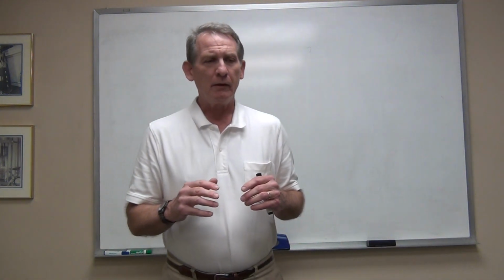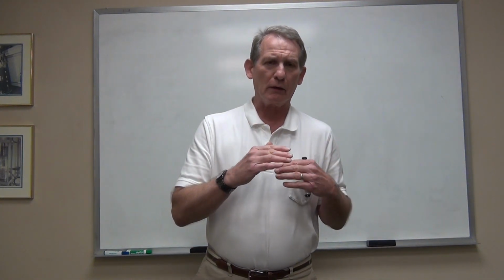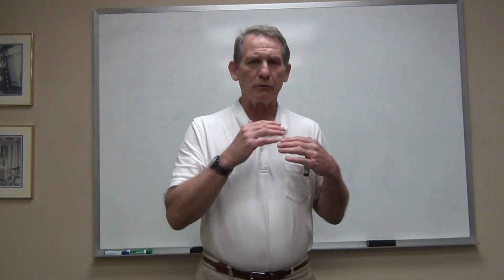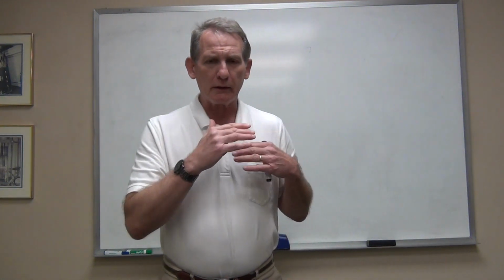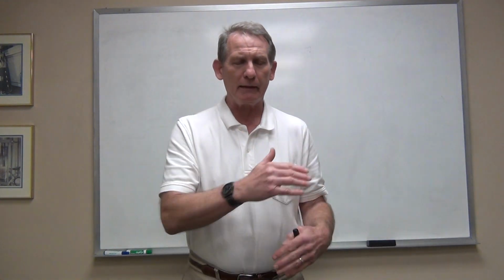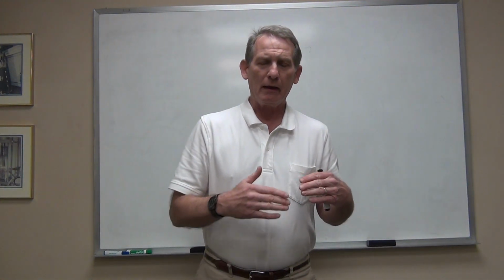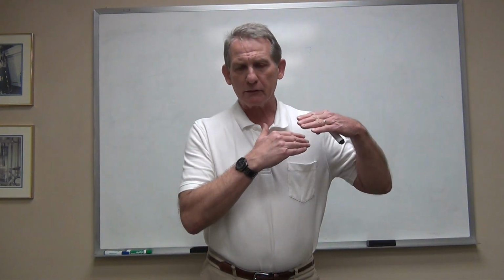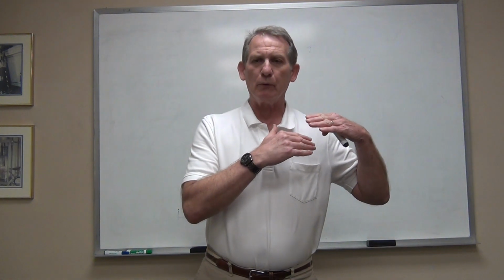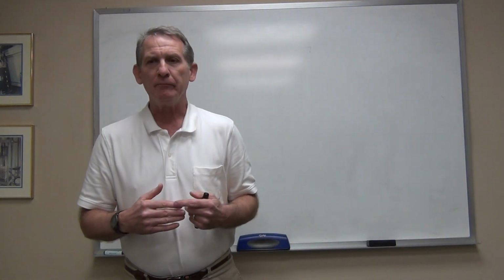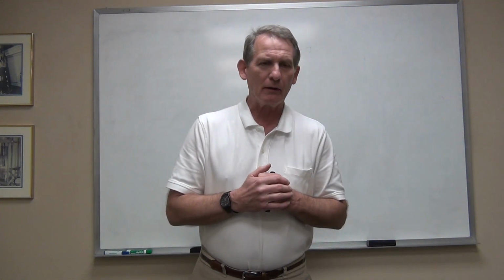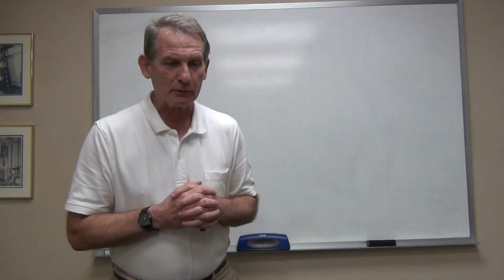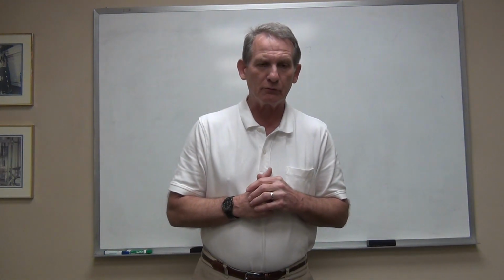It's fairly short. I know it doesn't read real easily, but spend a little time with the illustrations. Make sure that you get this idea that we are drawing a boundary around a perfect form. In other words, if we draw a surface as a flat plane, it will be drawn as a flat plane. And from that perfect representation, we project boundaries within which the actual feature has to fit. And that's not the hardest concept to imagine. What is hard sometimes is actually establishing those and making sure that your feature falls within it.